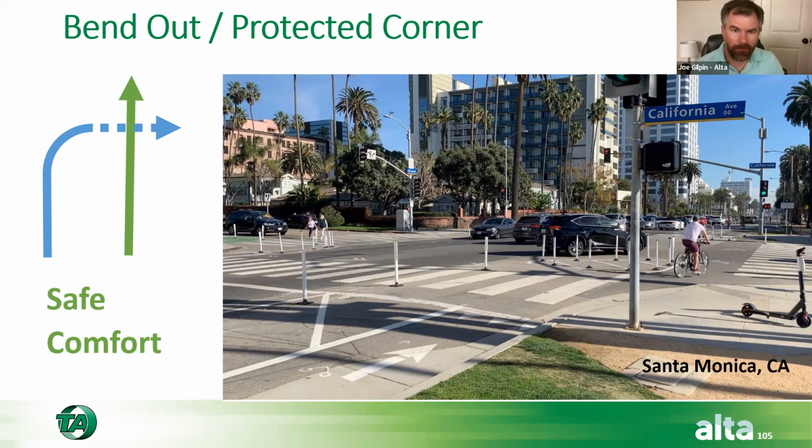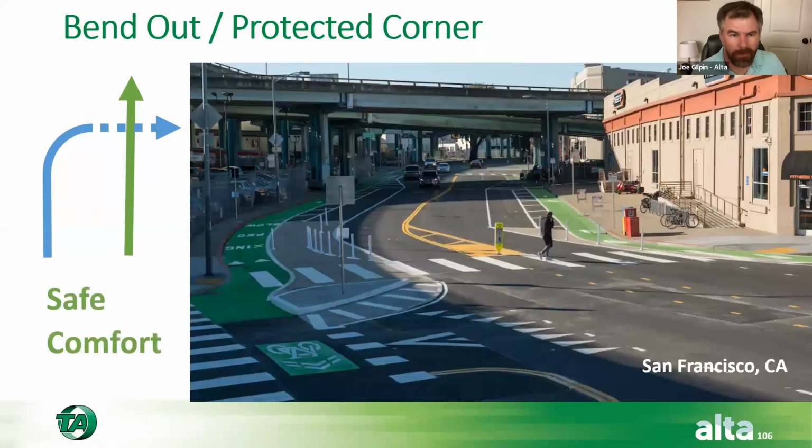And some local information that I can give you comes from SFMTA. They did their first intersection like this, I think back in 2016, 2017, kind of in that area. And they did a study looking at it. And so here's that setback right here around the corner. They have a little bit of a truck apron here too, so they can handle wider vehicles, but keeping most of the passenger vehicles working in this tighter corner here.